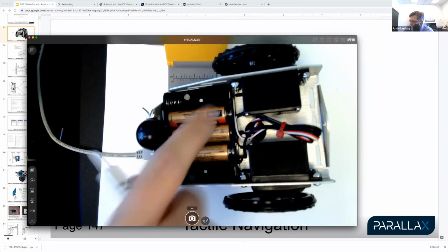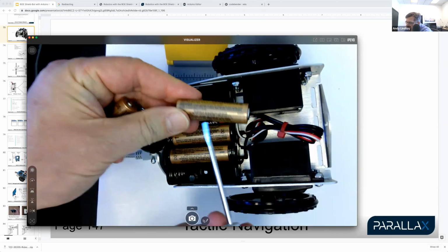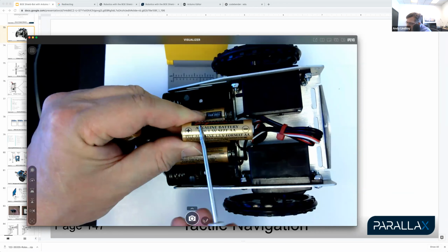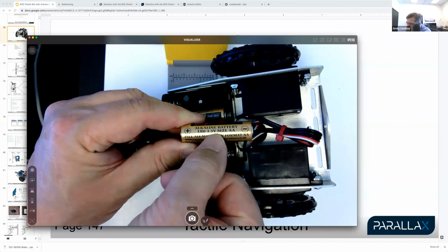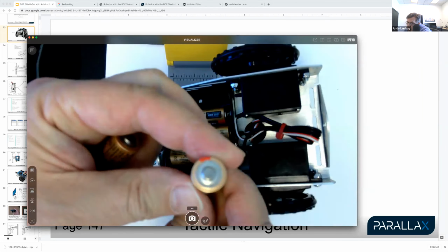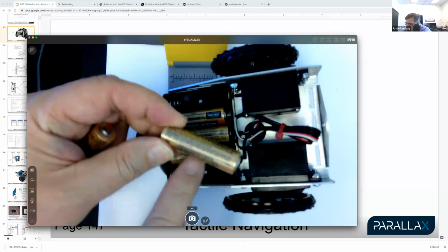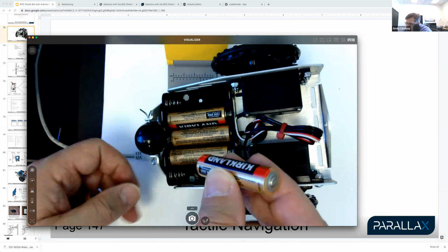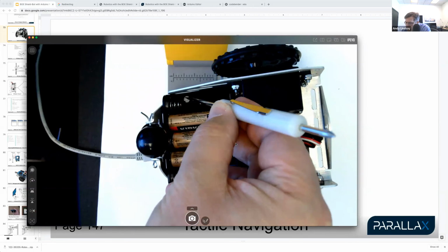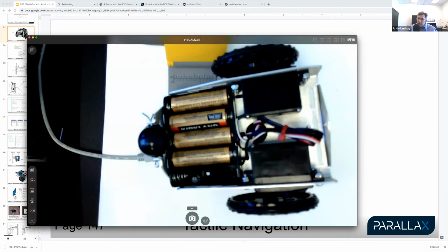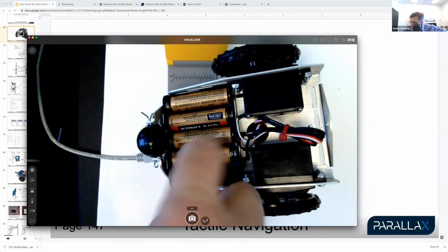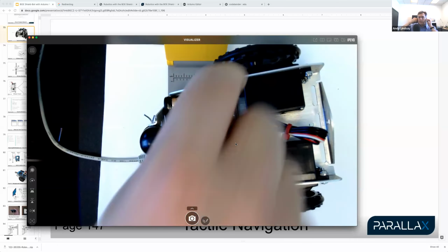The reason for that is what Felicia and I were talking about during the Zoom meeting, when we mentioned the battery tests and heating them up. This battery sleeve right here is really only a little thicker than cellophane. It's not very thick at all. Underneath it, you have a metal surface that looks like what you see on the ends. The problem is that the metal surface underneath the thin plastic is also connected to the battery as a voltage source. So if you have a metal screw here, it might actually nick the battery as you put it in. That might in turn connect the battery to the chassis, which is actually ground. So you might have some battery voltage that's a lot higher than 0 volts short circuited to your battery chassis. That's why it's very important.